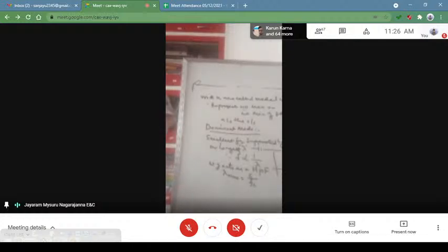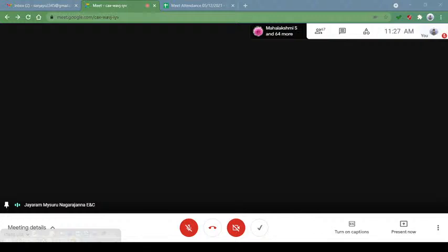So then the question arises, why should we excite this dominant mode inside the waveguide system? Whenever you want to transmit a TEM wave or TE wave inside the waveguide system, TEM wave is not possible. For TE or TM waves, we have to use a source. A source will generally be used to excite the different modes in the waveguide system so that the modes get propagated by multiple reflection inside the waveguide system.